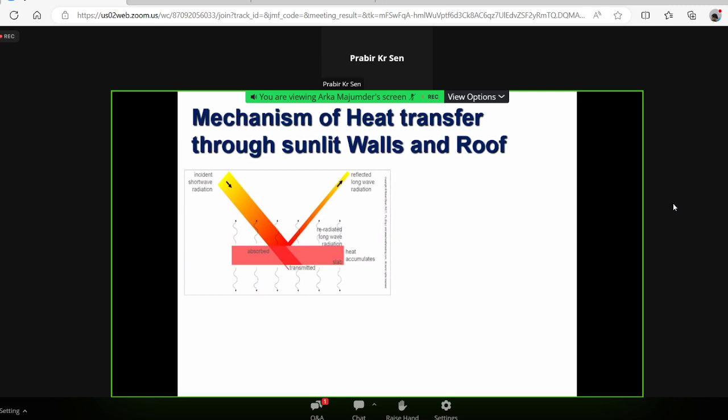When it starts radiating, some goes outside, some comes inside. And when the sun goes down in the evening, the wall remains hot and the radiation of heat still goes on. So then delta T is not that big. The sun has gone down, the outside temperature has fallen, but the walls are still hot and will keep radiating heat inside. So heat load will come in.